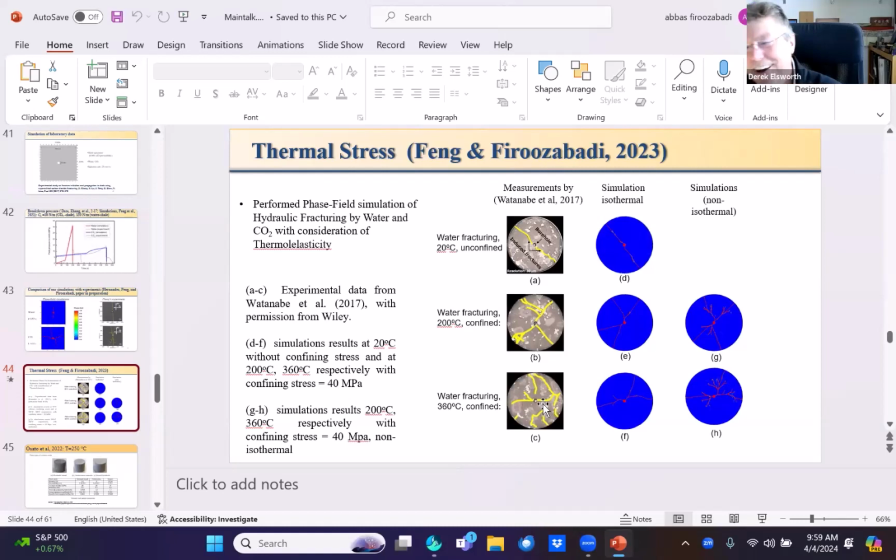I'm still on there. Well, we have experiments, and our working hypothesis with the CO2 fracturing was that the reason for the lower breakdown pressures was that you could get fluids directly into the tip of the crack because of surface tension arguments based on supercritical fluid. I think I will reject that right away, with all respect. We are using supercritical fluid, and you need two phases for surface tension. There is no meaning to surface tension here. I have seen that argument. There is no meaning to that, unfortunately.